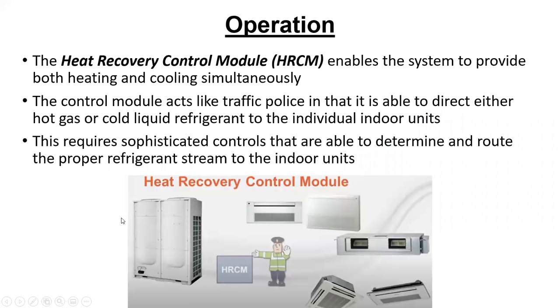Okay, the heat recovery control module, HRCM, enables the system to provide both heating and cooling simultaneously. The control module acts like traffic police in that it is able to direct either hot gas or cold liquid refrigerant to the individual indoor units.